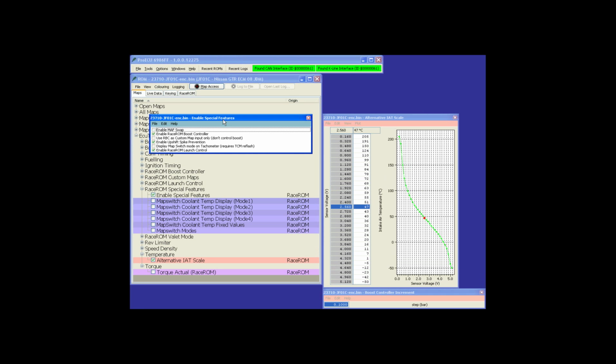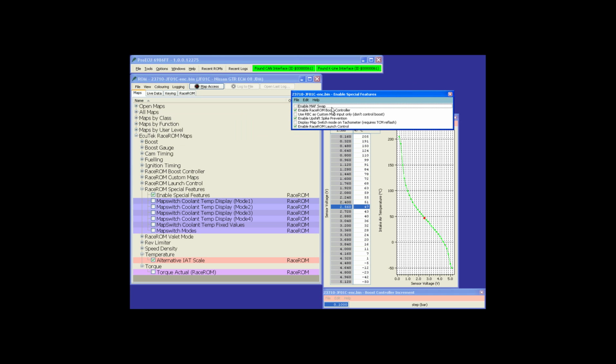They will all go up the wall if the engine ECU is looking at the wrong bank. So be aware when you fit big intercoolers, is it going to swap the MAF banks side to side? It's fundamental and it's important that they work properly. If you're not sure, check with the customer or check what intercooler he's got installed. Forge Motorsport, I think, is the main one that does it. There might be others out there that do it as well now. If you do have one with a MAF swap, use the MAF swap feature so that the ECU is looking at the right bank for the idle airflow balancing features like that.